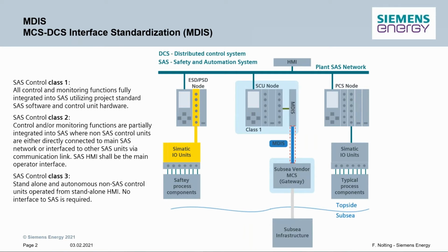In MDIS we call it a gateway. How the gateway or the MCS communicates to Subsea is actually independent of MDIS. So you could make a system where you communicate Modbus to Subsea, and then use MDIS topside. So upstream it is MDIS, and Subsea is independent of MDIS.